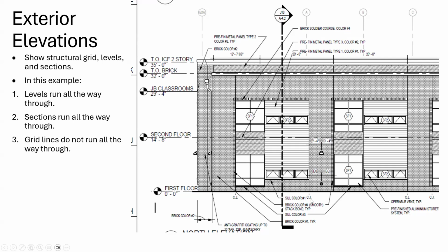Think about your masonry class that you had with me, the building materials. What did CJ stand for? Remember, I took the piece of paper and I tried to pull it apart and I talked about how the brick wants to crack when it expands and contracts. CJ stands for, the second word is joint, and control joint. Good. So that's a control joint that allows them to determine where the cracking is going to be.